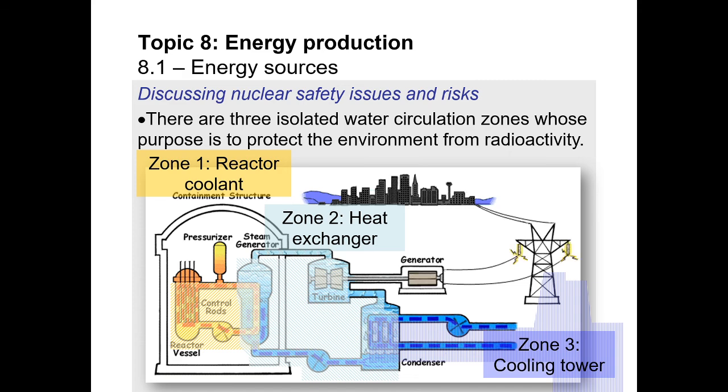Now, usually a concrete liner houses the reactor's pressure vessel. So that's right here. Usually this is a concrete liner, and it also acts as a radiation shield. Okay, so that liner in turn is then housed within a much larger steel containment vessel. The steel serves as a barrier to prevent leakage. So you have two layers. You've got the concrete layer and then you've got the steel.